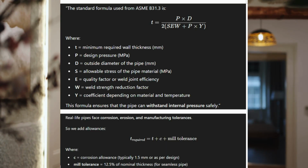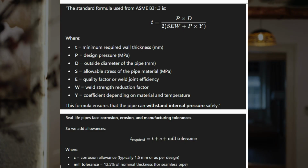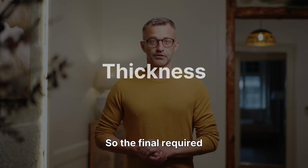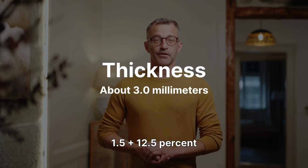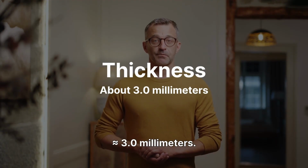But wait, in real-world applications, we must account for corrosion and manufacturing tolerance. We add these allowances to stay on the safe side. Corrosion allowance, usually 1.5 millimeters for carbon steel. Mill tolerance, which is 12.5% of the nominal thickness. So the final required thickness is 1.22 plus 1.5 plus 12.5% is almost equal to 3.0 millimeters.